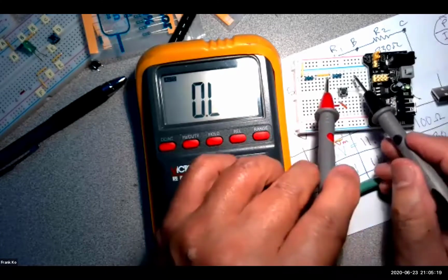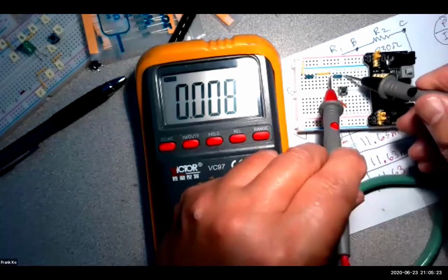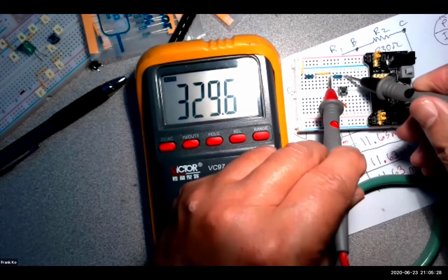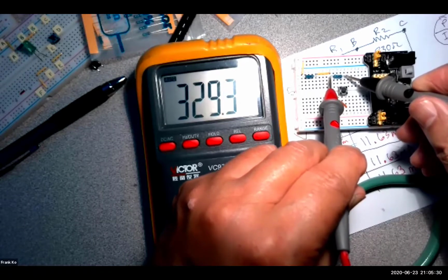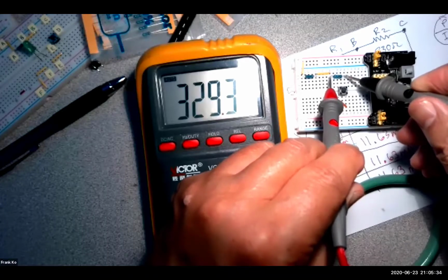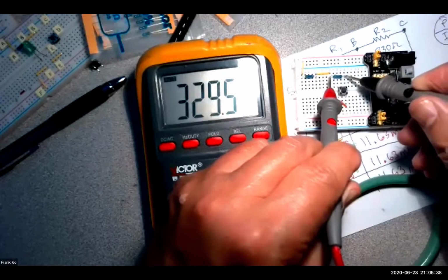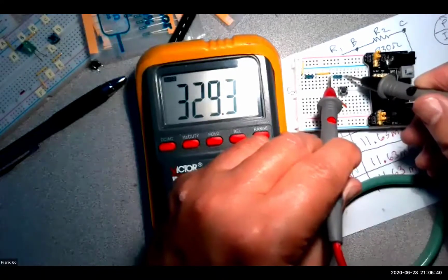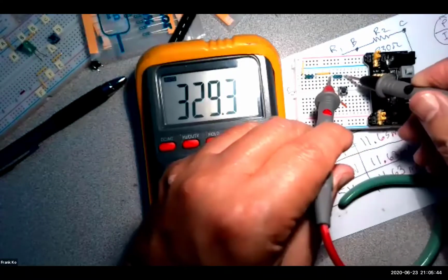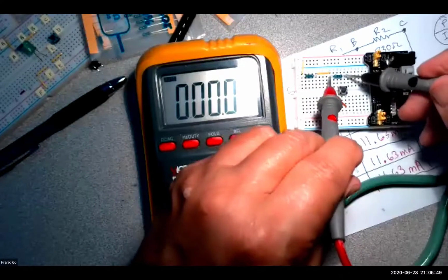And suppose I measure the resistance of the 330. Should be pretty close to 330. Let's see where this ends. 329.6. 329.3. And again, it changes slightly only because the amount of pressure that I'm putting on differs from one hand to the other, and I'm not pushing to the point where I'm going to break my pins, okay? But I verify I'm pretty much there.